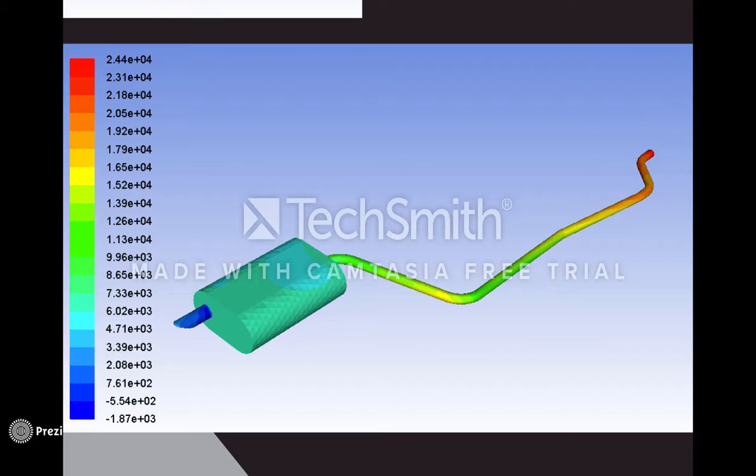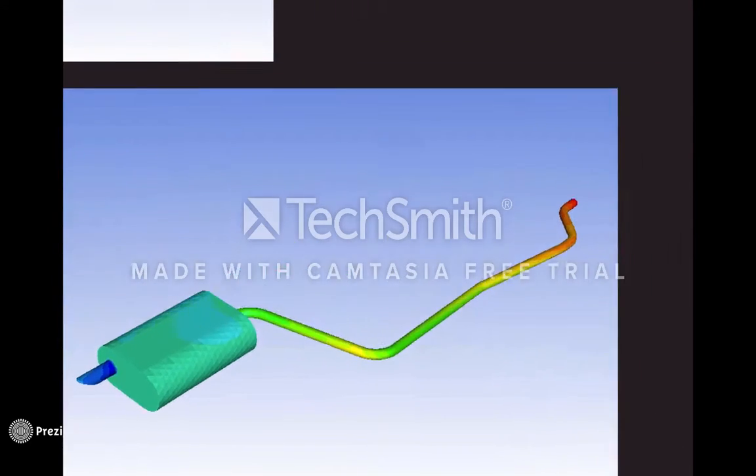So on to the things that everyone cares about, pretty pictures. These values are all in pascals, by the way. This is a look at the single exhaust pressure distribution, and you see a max here of 244 straight off the cat. And looking at the total distribution, you'll see that it is higher than the dual exhaust, though not a lot higher.